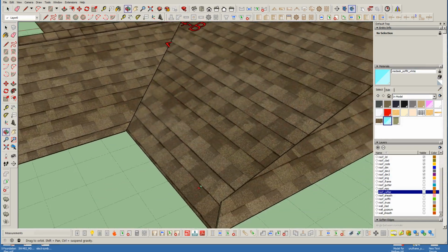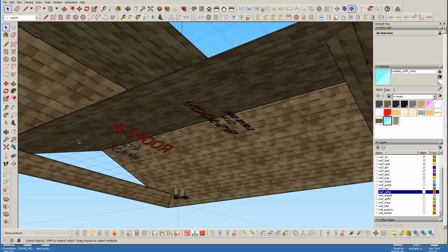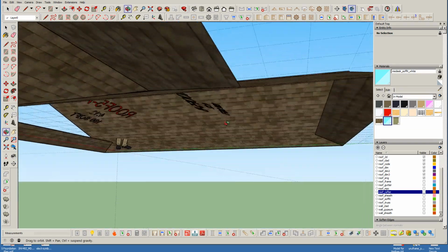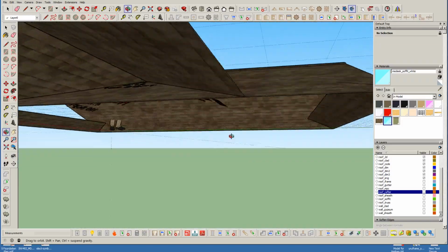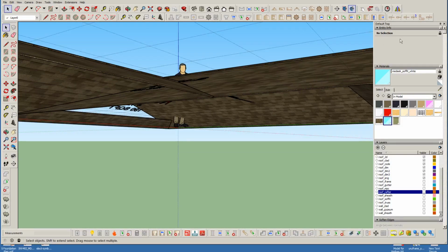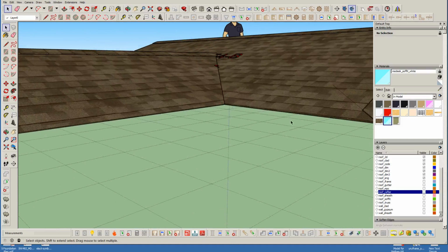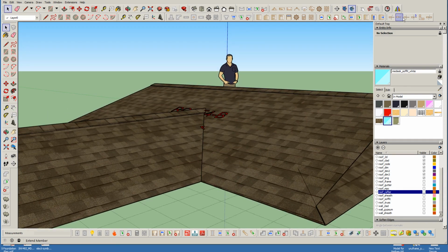But now, the first thing you're going to say is, well, hey, the problem is I've got this chunk of cladding that I no longer need, right? That cladding is not being used. And yes, you're perfectly right. So what I'm going to do is use what I call the trim to tool to deal with that. Now if I were to try to trim this primary roof's cladding with the regular trim tool, it's not going to work because it only allows me to select one face. Okay, that's no good. What this other one does is it allows me to select two faces.